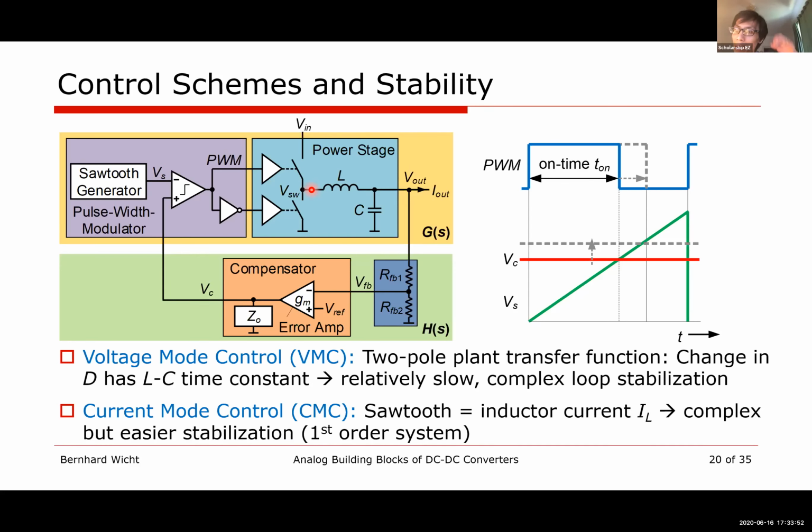Frankly speaking, I just want to talk a little bit about this because recently I see some new topology. They mention the hybrid converter. So they move the inductor from the output to the input. In that case, they transform the input and the output current to become continuous. And hopefully we don't need any external LC filter anymore, to reduce cost. Yeah, that's one of the benefits.